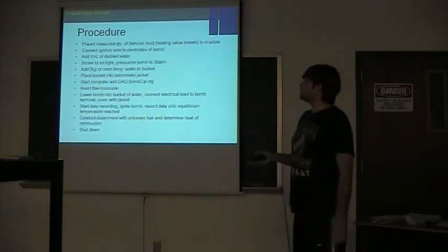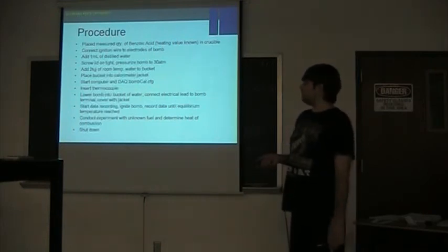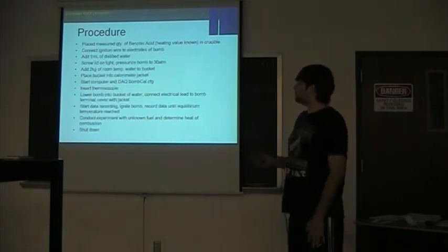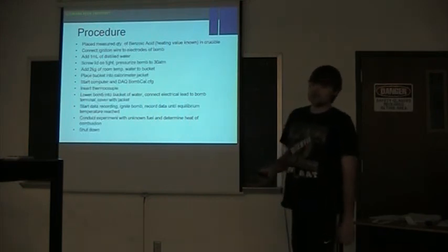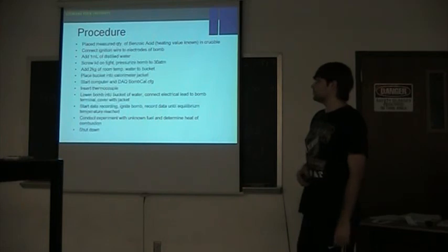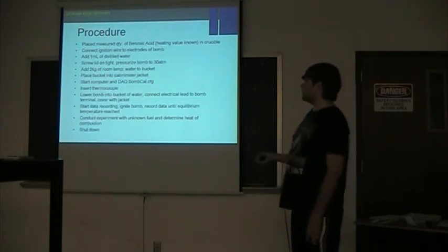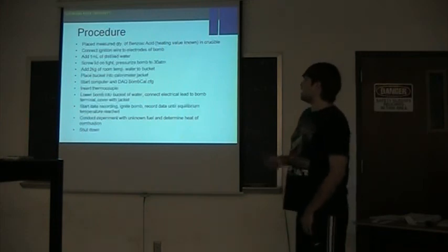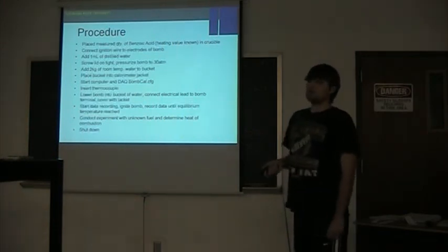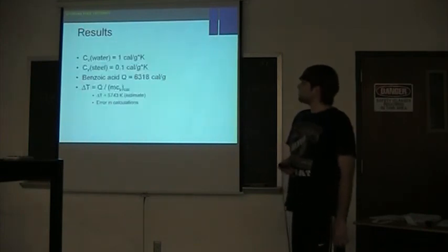You add your water, place the bucket down in there, start your computer, start your software, insert your thermocouple, and start recording data. When you record, you always want to get baseline data first. That's what any experiment in general will do. You want baseline data, and then you ignite the bomb, and then you'll see a jump in temperature. From this jump in temperature, we can calculate our thermal capacitance, as well as when we conduct the experiment with our unknown fuel, we can use that to determine our heat of combustion.